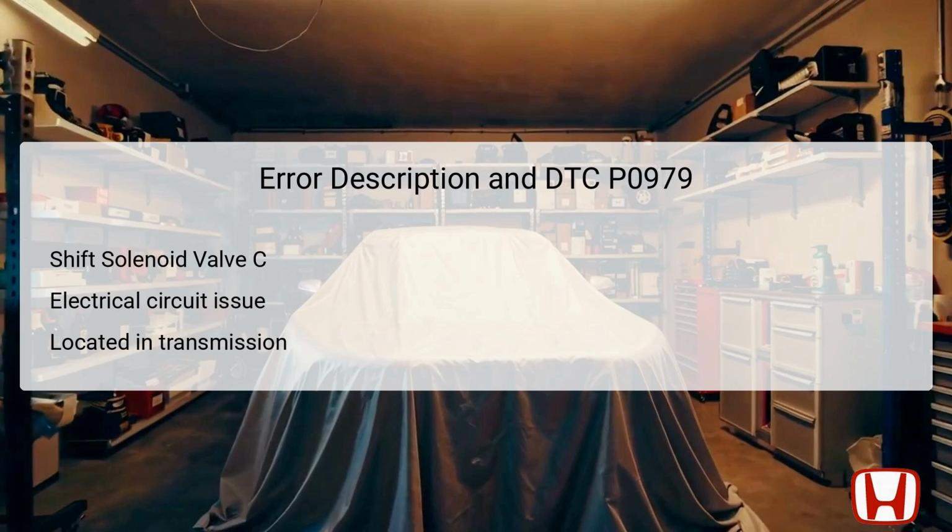This solenoid is responsible for directing the flow of transmission fluid, enabling the transmission to shift correctly between gears. The electrical fault may arise from issues like damaged wiring or poor connections, as the code indicates a circuit problem rather than mechanical failure. The solenoid is located within the transmission assembly, generally connected to the transmission control module and other solenoids, thereby giving it a direct role in gear shifting.